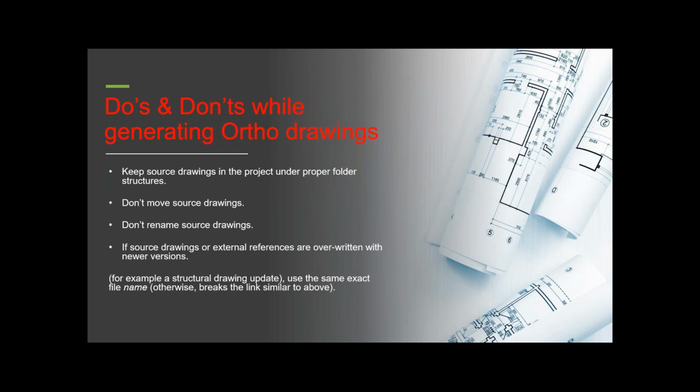Do not try to move those drawings outside of the folder structure, especially in Windows Explorer. As long as you do it within the project manager, it is still fine, but still not recommended to do on a regular basis. You set up your project up front, how you want to display your folder structure, and operate in the right folder structure in order to avoid any challenges with generating ortho or ISO drawings at a later time.